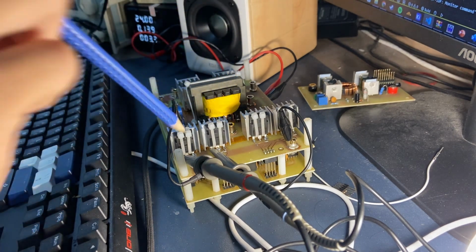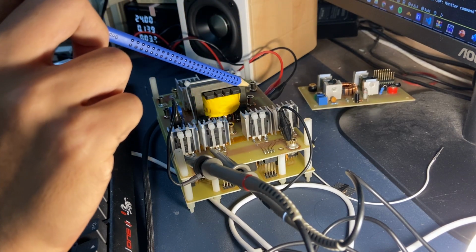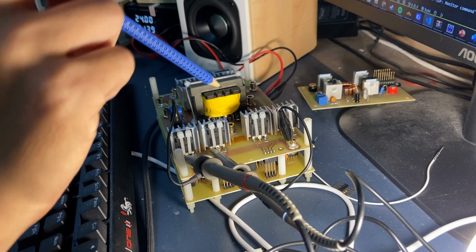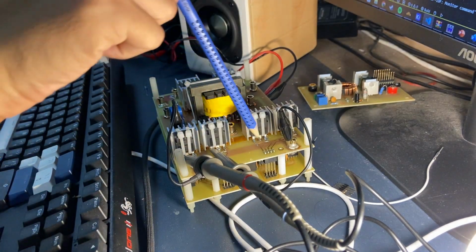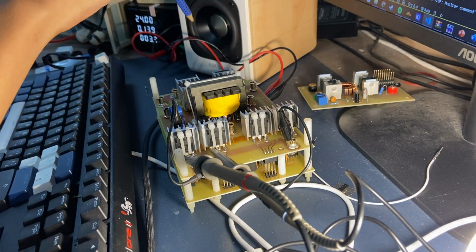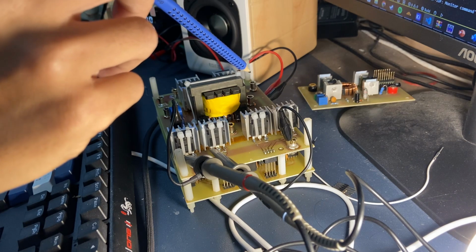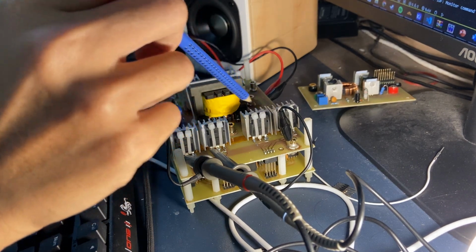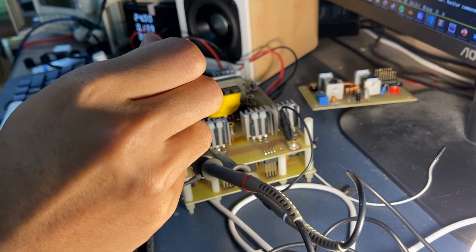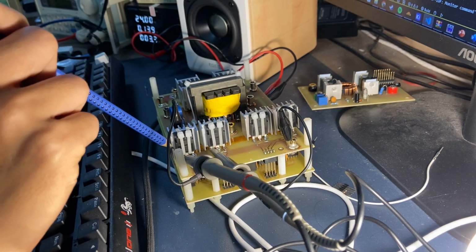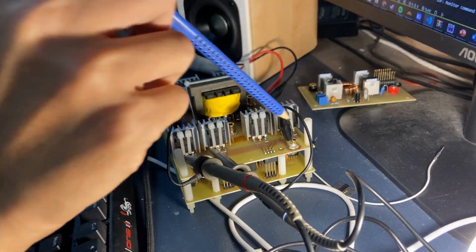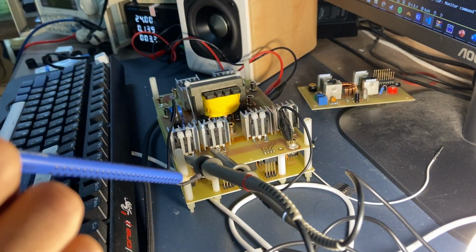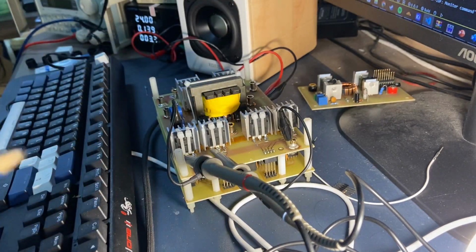This is because my oscilloscope is not isolated for the ground. So if you have a high voltage between the switch that flows, it means that when you connect to its gate and source of the MOSFET, you can short circuit through your oscilloscope and fry your oscilloscope. So in here I just show the signal. Okay, so we go back to the program.